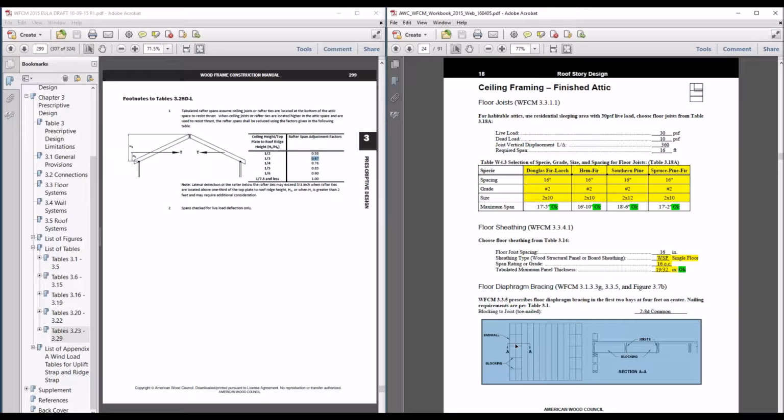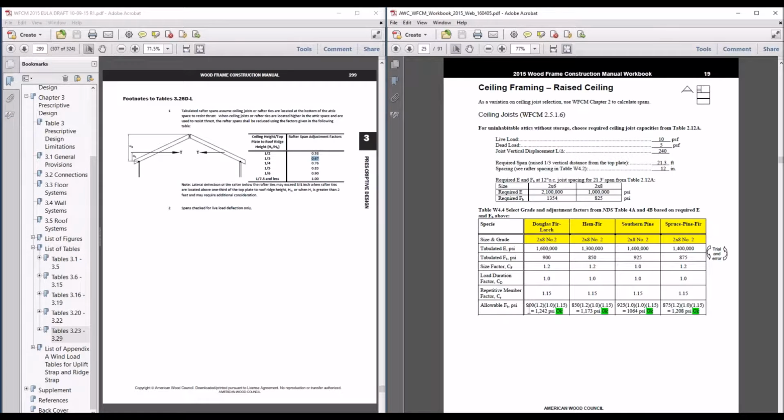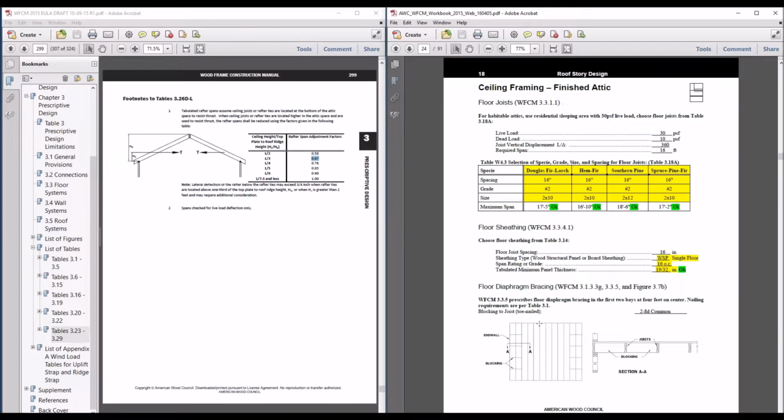And again, that just stiffens up the end of that diaphragm to get the loads from that gable end into the floor diaphragm so that it can be shared then into the shear walls. So just note there is some prescriptive application there for those diaphragms. And that reminds me, I'm going to jump back there just one more time to talk about that.